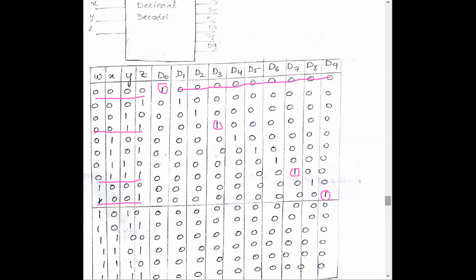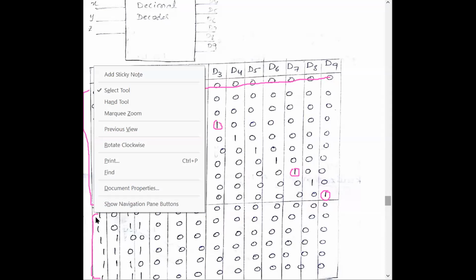And what about the numbers after 9? In BCD, there are only the numbers 0 to 9, and the remaining numbers 10 to 15 are unused, invalid numbers. If you write a 4-bit number, we have 16 possibilities, but only 0 to 9 are the BCD representation. The numbers greater than 9, that is 10, 11, 12, 13, 14, 15 in their binary equivalents, are invalid.